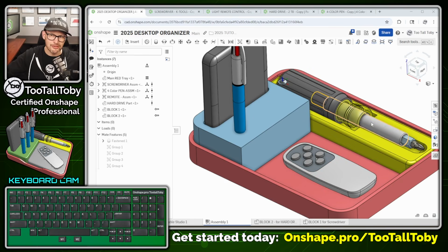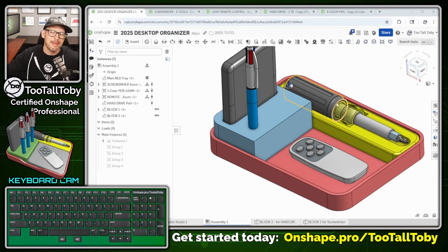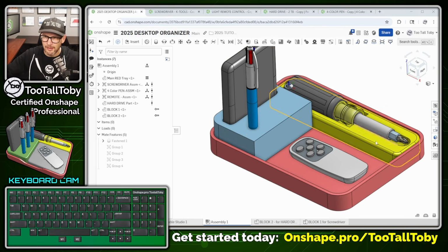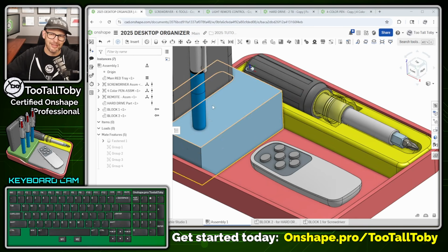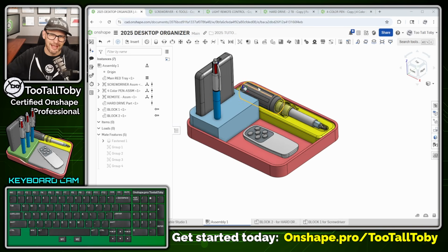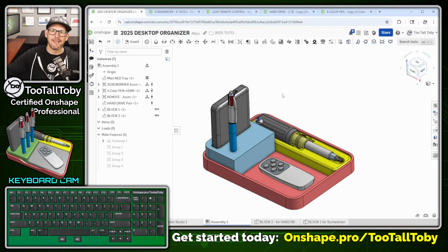Boolean in that application. So if your plan is to draw up some of your own parts, maybe you want to consider making a relatively simplified version of those parts and think ahead about how much easier that's going to make it to do a Boolean. If we try to do a Boolean with some of these components, we might end up with internal geometry because there's cavities inside of these parts. But with the hard drive, it was just a nice solid chunk of plastic. So it was really easy to do a Boolean because it's a relatively simplified version of the source model.